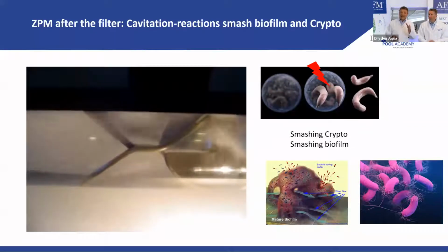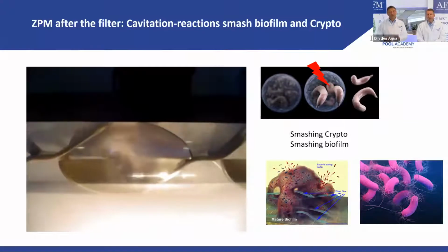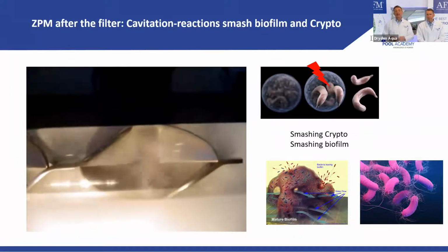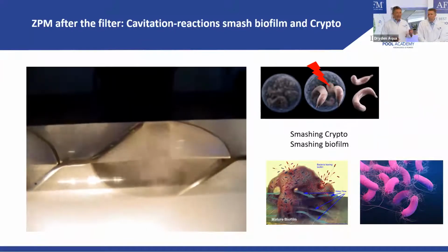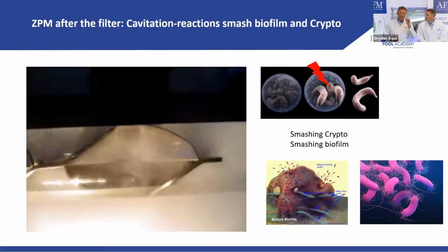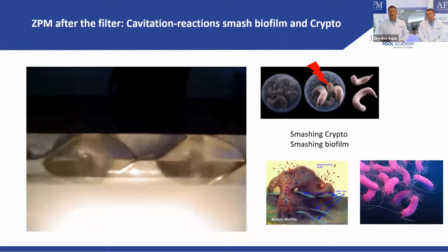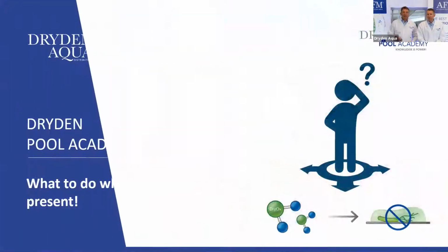So something good. You will lose pressure here. You have to drive this a little bit more aggressively with 200 millibars, 300, ideally 500 millibars of pressure loss, and that will need a little more energy. This is not good, Philip, right? Well, actually, you don't lose it. This energy goes as heat into your water. But yes, you need a higher pump to do that. So, yeah. Good.